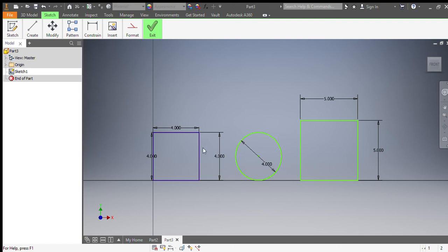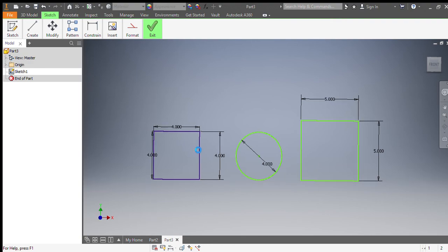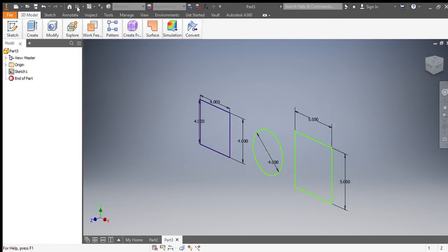You can click OK. If you click cancel, your part is not saved. So you click OK, and then your save window pops up. Once again, you find your G file, and then you title it your name dash whatever project you are creating in Inventor.